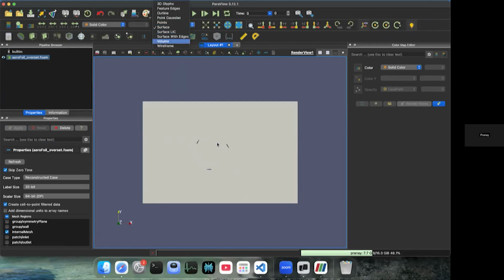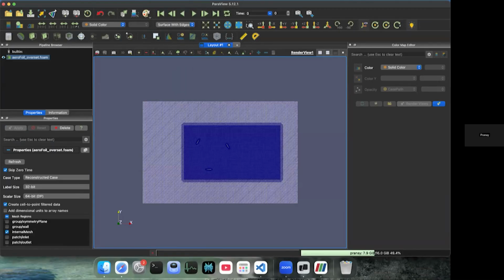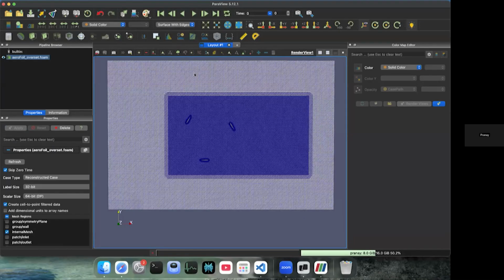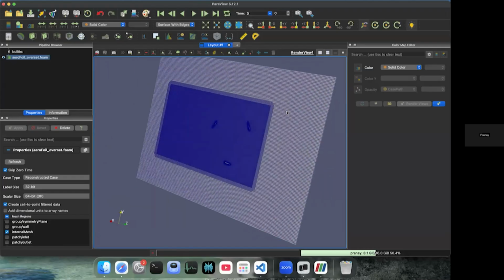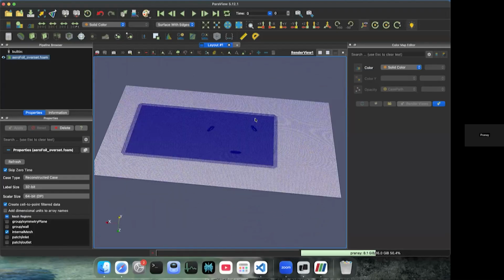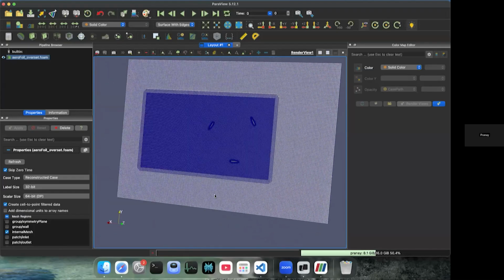This implementation is very quick since we are only extruding by 1 unit in the Z direction. Now you might be able to see how the solid region which was seen previously is eliminated and perfect aerofoils are coming into the picture. You might see it is see-through.